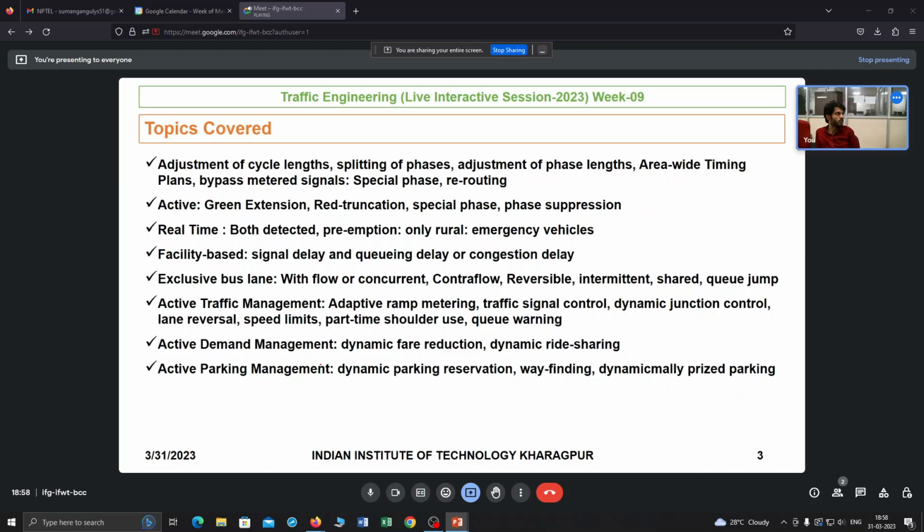what other methods are we also discussing now? The maximum trial cycle method or something, that name. So based on that we will design our optimal cycle length, C, right? Optimal cycle length. So if we know our optimal cycle length, I may want to change the cycle length itself. So I want to increase the cycle length so that buses are not facing delays.